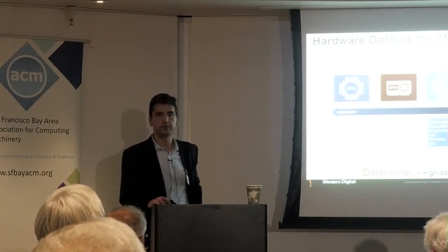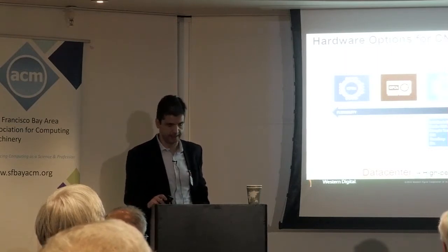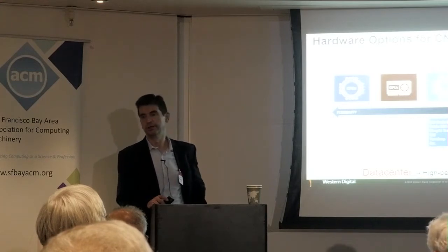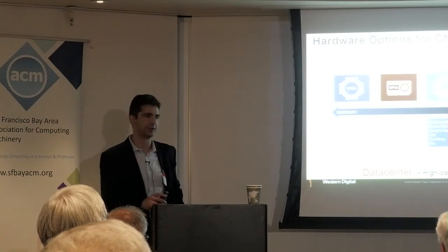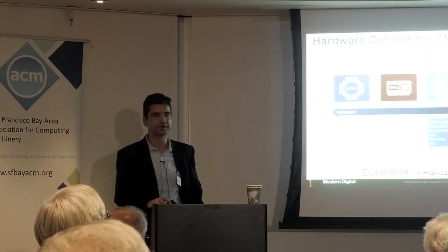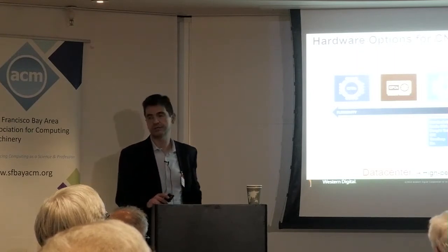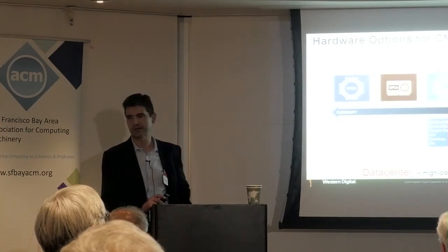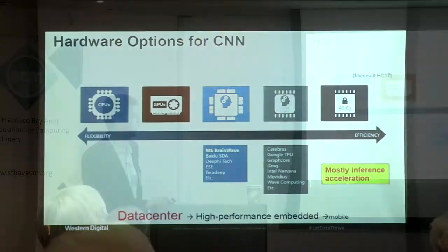Depending on what the application is, maybe your application is reading a mechanical counter that reads the power consumption in a household. Well, that needs to be read only once a month remotely with a little camera, which clearly has super low throughput. But maybe your application is video surveillance at San Jose Airport with 2,000 cameras, everything in real-time recognition, then obviously you need beefier hardware.